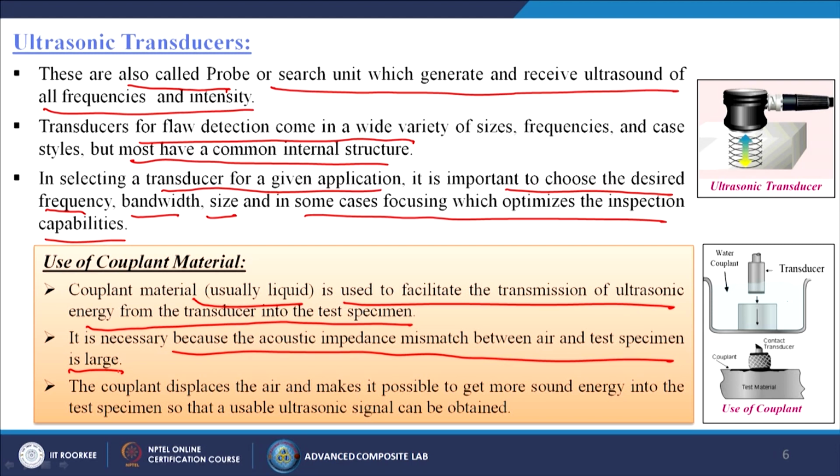So, that is why nowadays you can see that we are using ultrasound heavily for medical purposes, right. We are doing ultrasound testing, and if you see properly, when we are doing that kind of testing, we have that probe, and whichever body part we are going to test, we simply rub that probe onto that surface, but not in dry conditions, because as I told already, ultrasonic wave propagation requires some media. So in that case what are we using? We are using some kind of gel material, so that the ultrasonic wave passes directly through that gel into your body.